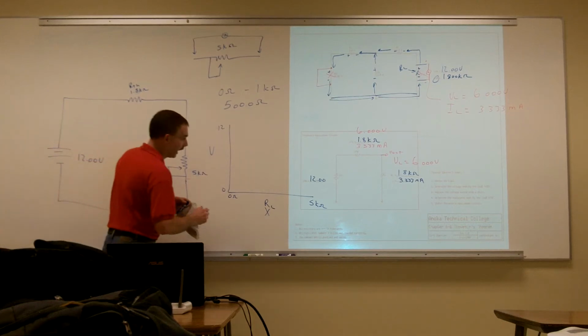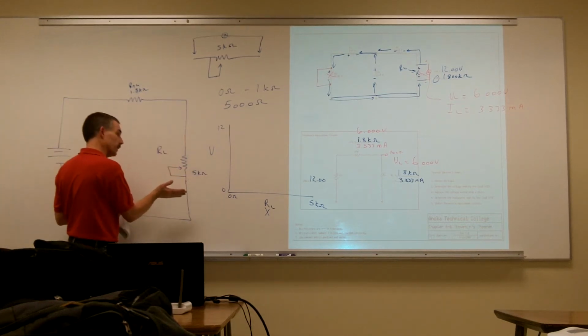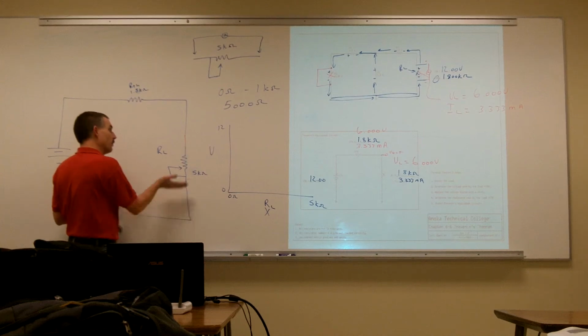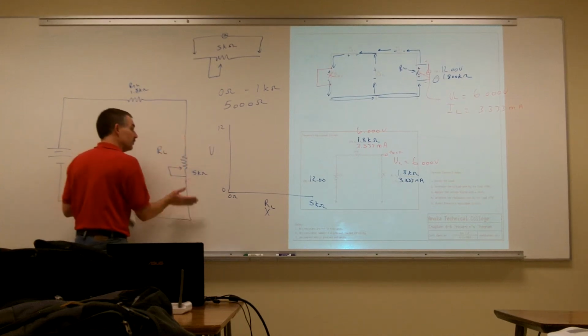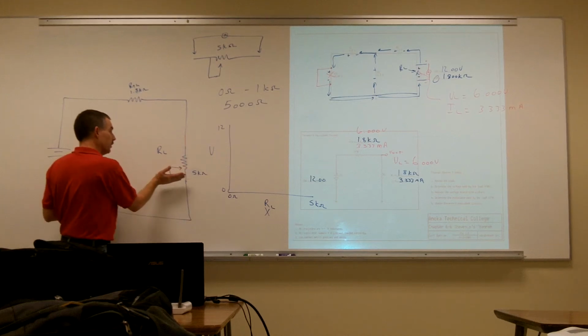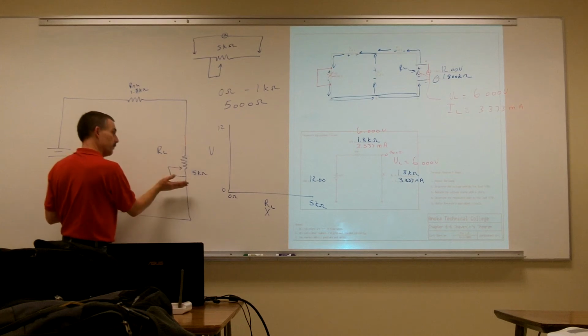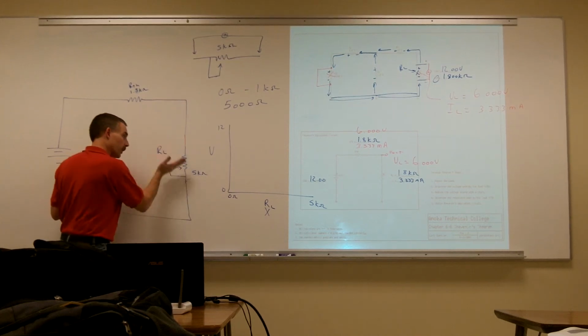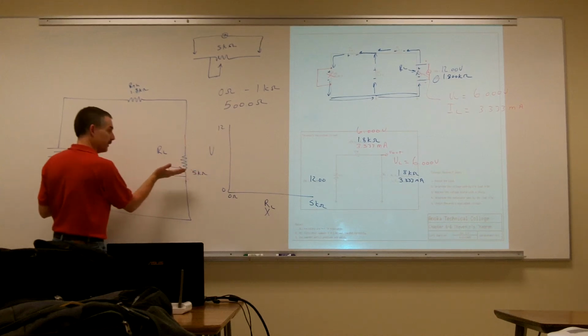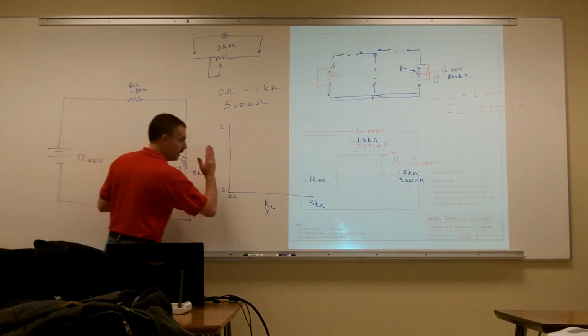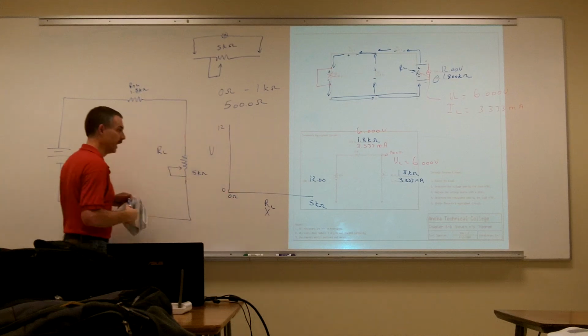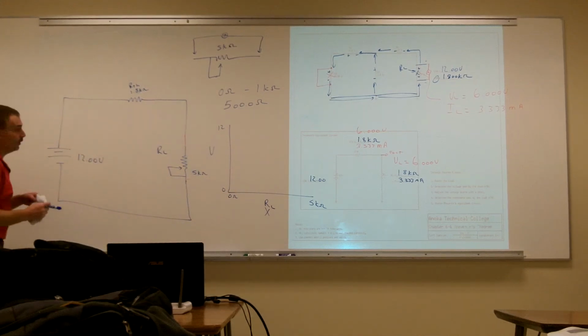We're going to work our way backwards, because typically when we're working on circuits, we like to have the most resistance and then start decreasing it. We never really want to put a short into something unless we really know what's going on with the circuit. So when analyzing a circuit with a potentiometer, we always want it at maximum resistance. But sometimes that means we have to graph our data in reverse order.